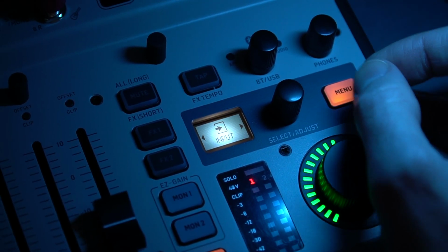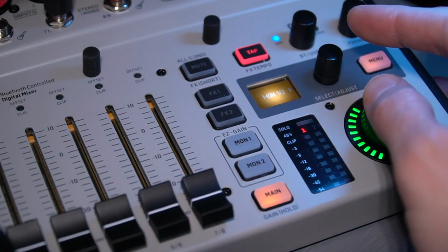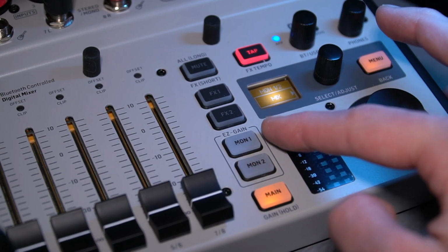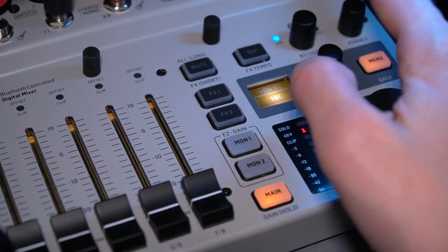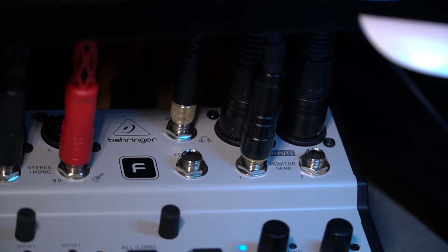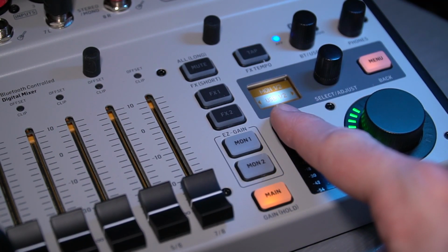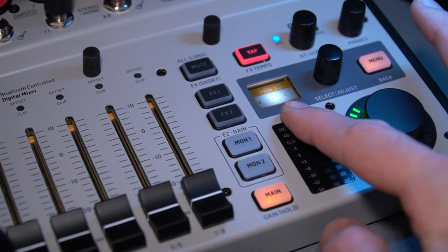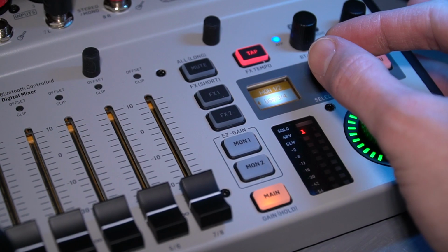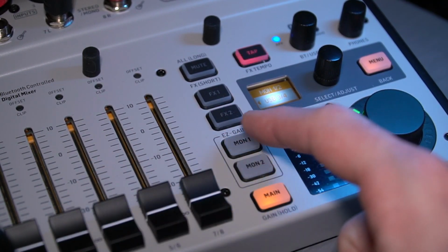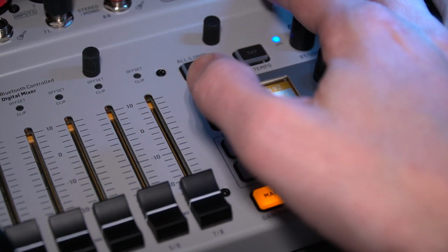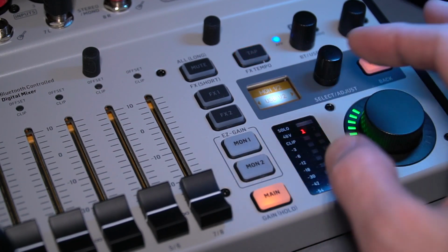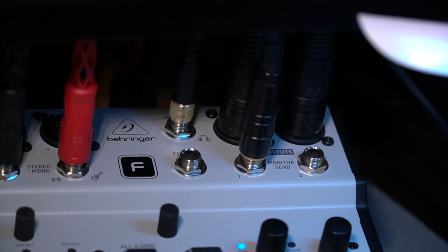We have some new output routing options as well. Let's go take a look at what those will do. So for monitor 1 and 2, we can now select between having the mix, which would be monitor send 1, monitor send 2, going to those physical outputs on board here, or we can choose to have the USB 1 and 2 return go directly to those physical outputs. You can also choose from USB 3 and 4. So the choice now is to route either the mix that you're sending to monitor 1 and 2 from the mixer out of the monitor sends 1 and 2, just like normal, or you can route the USB returns 1 and 2 or the USB returns 3 and 4 directly to those physical outputs.